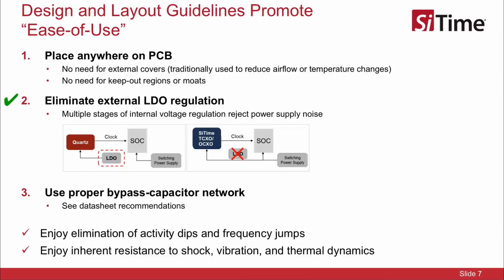SiTime's precision oscillators also include multiple stages of voltage regulation to minimize the influence of power supply noise, which saves designers the expense of adding an external low dropout regulator. Lastly, a proper network of bypass capacitors should be used as documented in the datasheets. Designing with SiTime's precision oscillators is not only quick and easy, but extends the inherent benefits of MEMS over quartz to the design, including no activity dips or frequency jumps, plus a strong resistance to shock, vibration, and thermal dynamics.